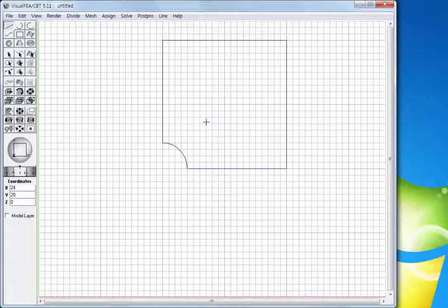The next step is to generate a planar mesh over the region bounded by the curves. The density of the mesh is determined by the division of the boundary curves. In this example, the 2 lines bounding the top and right sides are divided into 8, respectively.